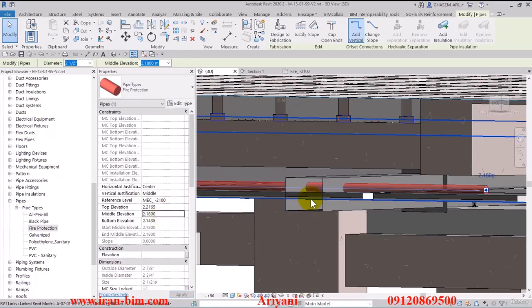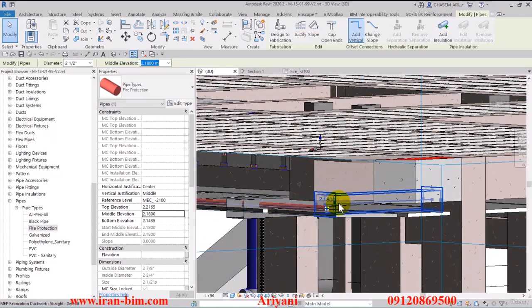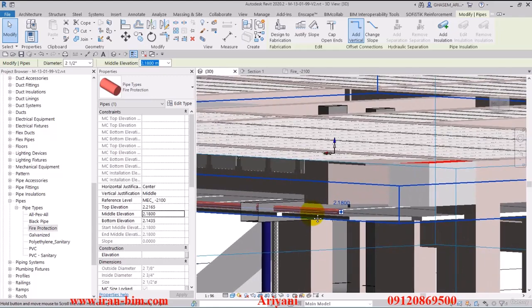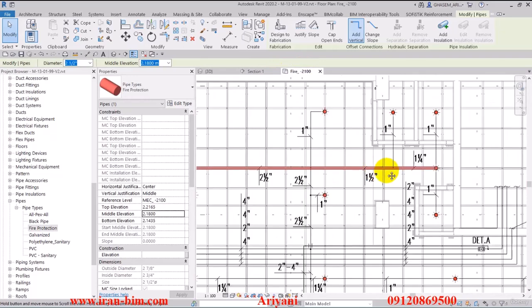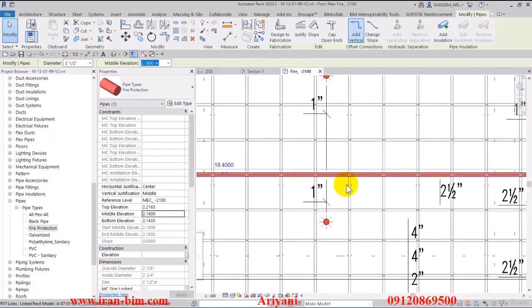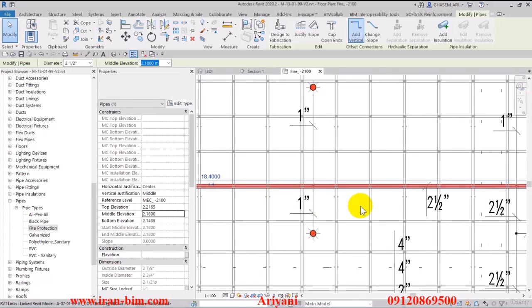So here we'll need to reserve our first priority for fire protection and get the placing of that fixed, and as they say, freeze it, and then we can get to the adjustment of the duct. So we shouldn't make any changes to the order of the priority, but we could make changes only and only if we can get the confirmation for the fire protection settings as well. So these are some implementation tips which we need to take into account on top of the modeling itself.